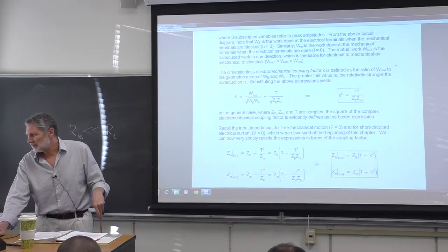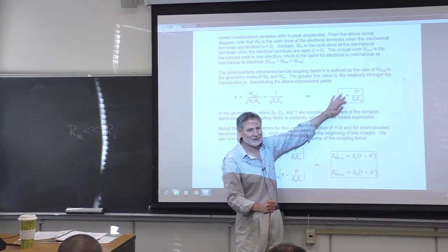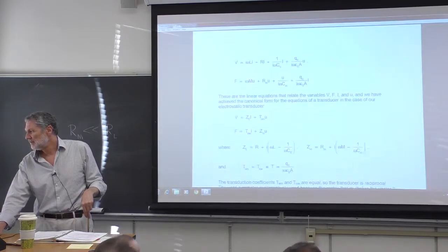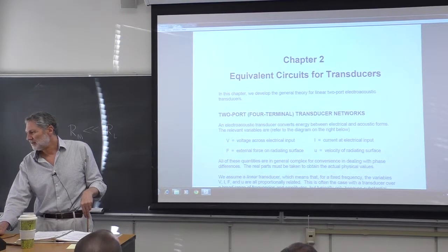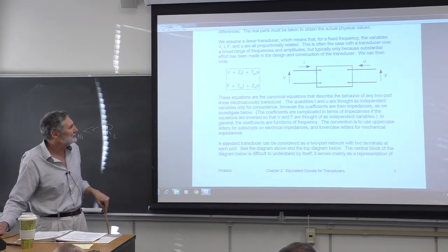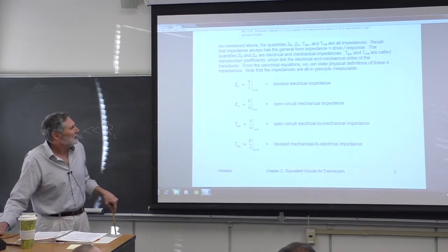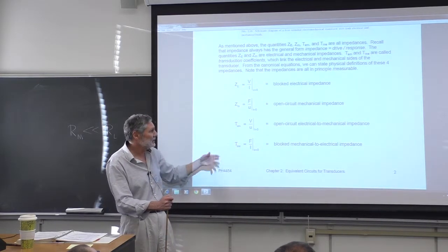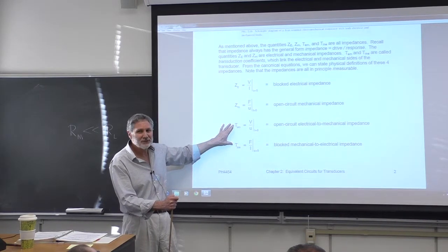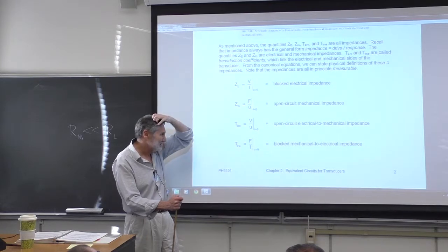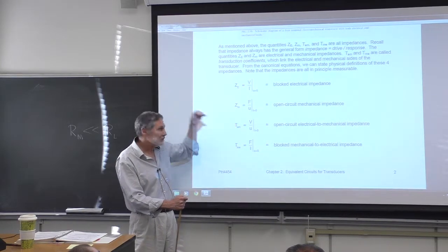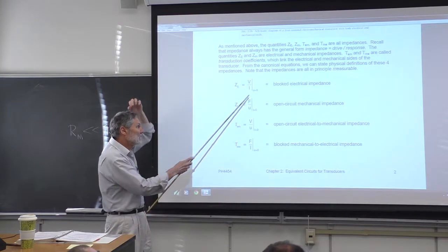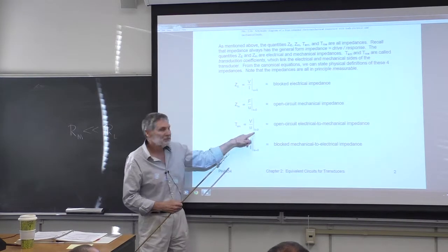Okay, well, the next thing we want to notice here, this is part of why this is such a nice dimensionless quantity. I want to remind you of the first lecture of this chapter, where we went through, okay, everything's linear, that's nice, cartoons, and then we physically appreciated these quantities here, these impedances. And I didn't realize until this time through the course, these are impedances too, they're transfer impedances. I don't think I realized that before, which I should have. These transduction coefficients have physical meanings when you look at limiting cases of either blocked, no mechanical motion, or open circuit, no electrical current.